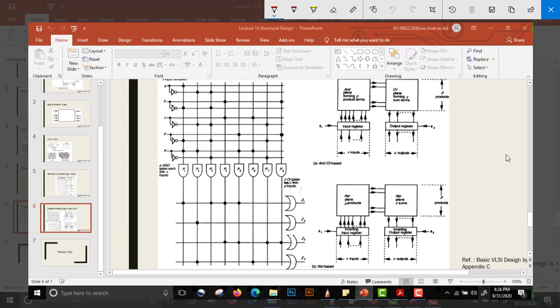we can see that here we have inputs A and NOT gate outputs A bar, B bar, C bar, D bar, E bar. That is, this is a 5 input logic. It can perform a 5 input logic function, and it can give 4 outputs. Now it has lots of AND gates and OR gates. For simplicity, each of the AND gates shows one input here. Actually this is not one input, this is a multiple input AND gate.